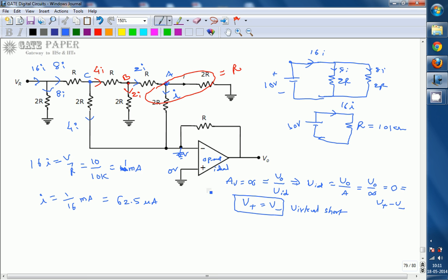Okay. And now if you want to calculate V0, V0 is nothing but the voltage from the V0 node to ground. From this node towards ground is nothing but this one. So if you know the current flowing through this one, assume that one current is flowing in this one, because no current flows through internal nodes. So whatever currents are coming in this way and in this way, they get added, and the same current is flowing through this R. Assume that this one is capital I, whereas the previous one is small I. Otherwise you can go with I1.